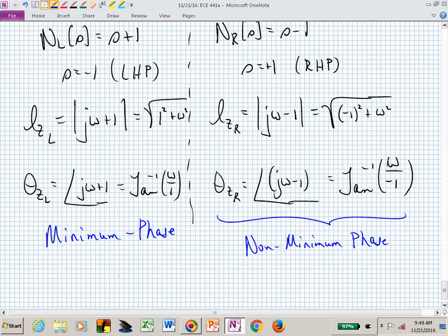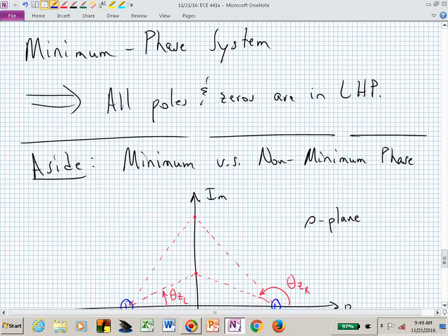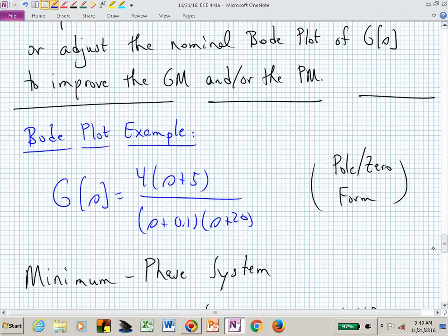And what I want you to now do for homework on your napkin is sketch that Bode plot. What are the steps? How would you do that? First, you'd want to put it into a time constant form. Once it's in time constant form, now you have the pieces that you can work with. You can find the magnitudes individually and add those up. You can find the phases. Where's your phase going to start? At what angle? At low frequencies, what's the phase of this system?